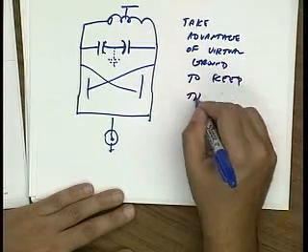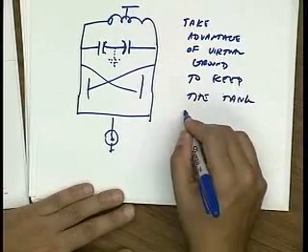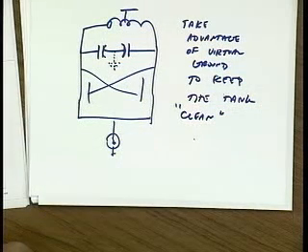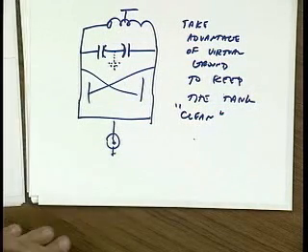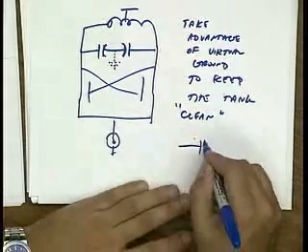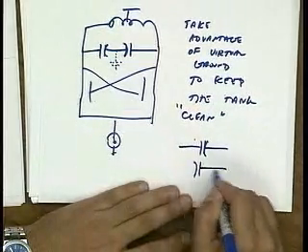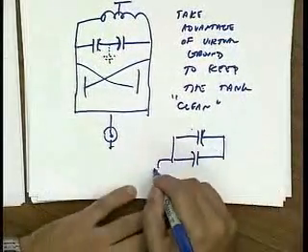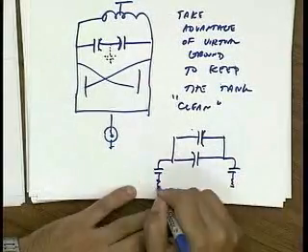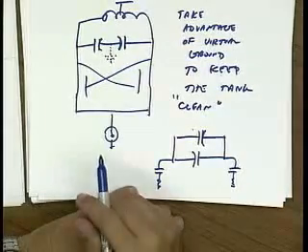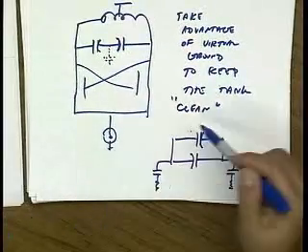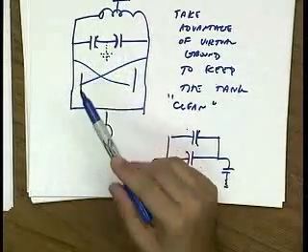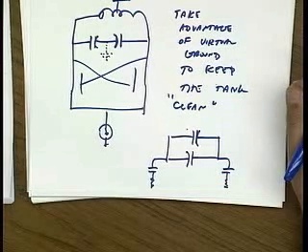Let's say to keep the tank clean. Yes? Well, if we put two capacitors parallel to each other, are they the same? Yeah, you could do that as well. For instance, I could have a structure like this, right? But then you still get the bottom plate, so you still would have your bottom plate on both sides now. And preserve symmetry, but you still get the loss. Okay. In fact, this is nicer because you just split the capacitor in half. Here you actually have to use twice the capacitance, so you do pay a penalty for doing that.